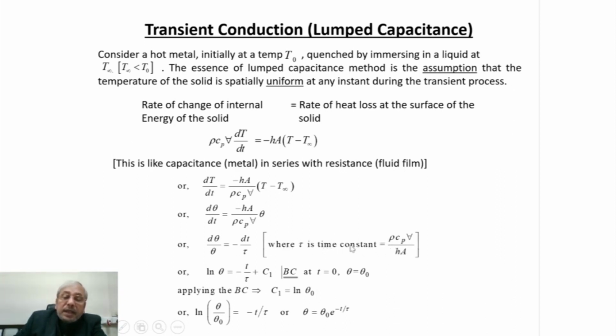It can be expressed in seconds, and time constant is a very important parameter for all temperature measuring devices. As I said, if we do the analysis of fundamental dimensions, it will be seconds, and a lesser value of time constant is always beneficial, because the response of the device will be faster.